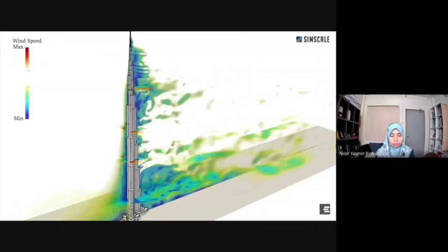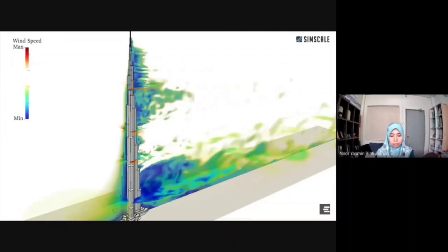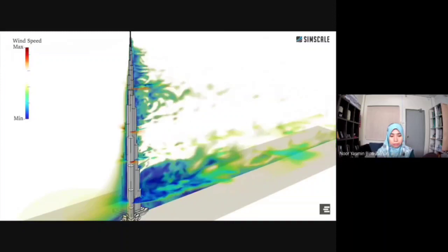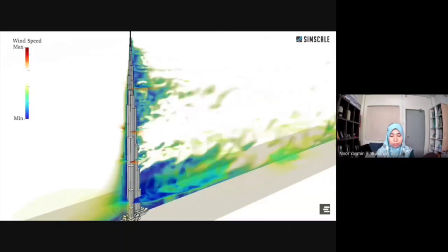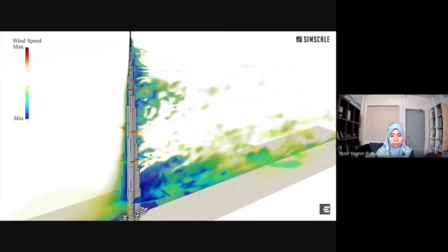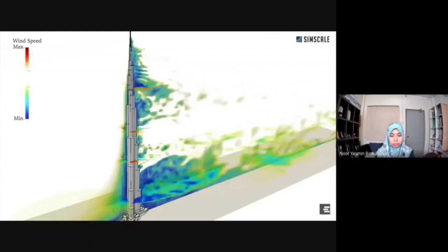At the very top, the wind speeds are the highest, but the cross-section area is rather small due to tapering, so forces are thus small also. Combined together, the structure is very well optimized with respect to wind loading and is effective in taming the wind.